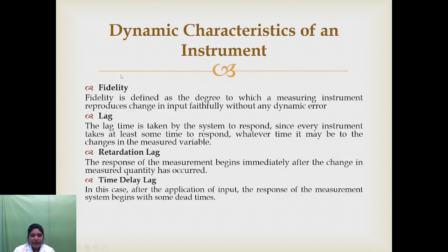Next is fidelity. The fidelity is defined as the degree to which a measuring instrument reproduces a change in input faithfully without any dynamic error. That is, it produces output like that of the input. So that is called fidelity. And lag is a time delay in which the system takes some time to respond. It comes under two categories, retardation lag and time delay lag.